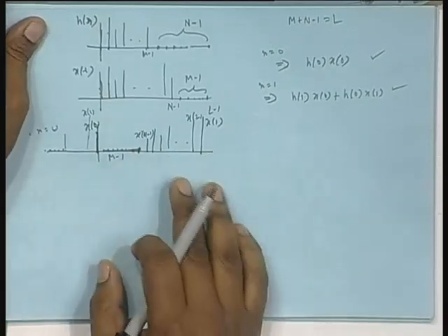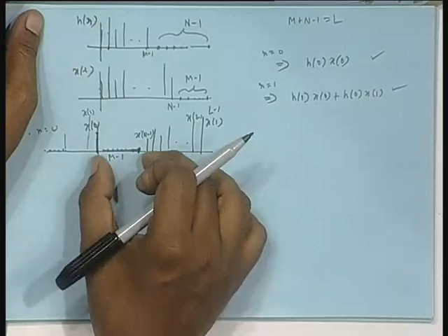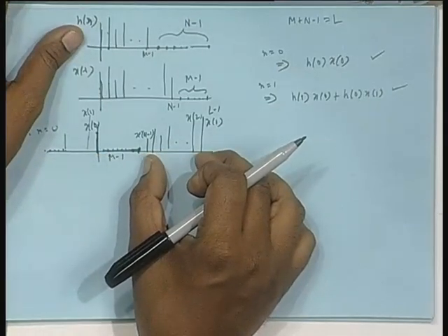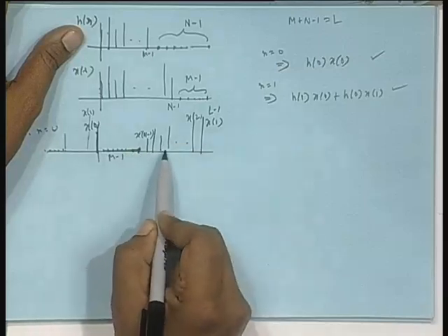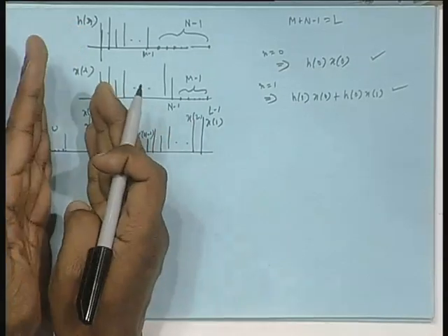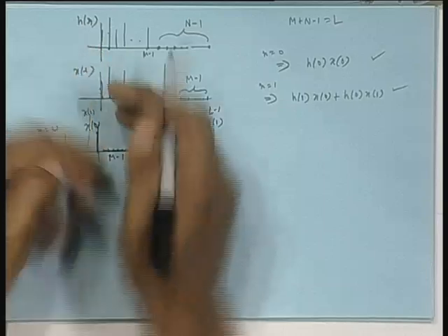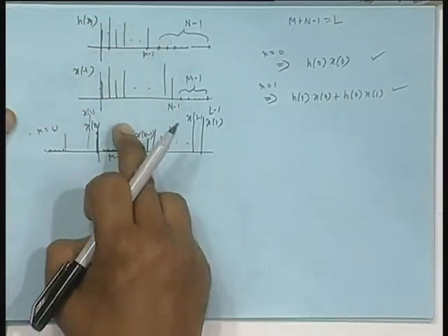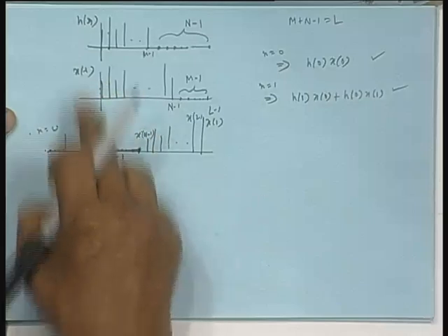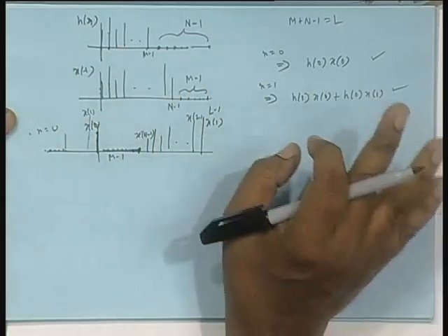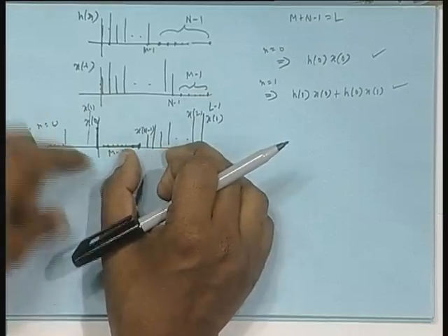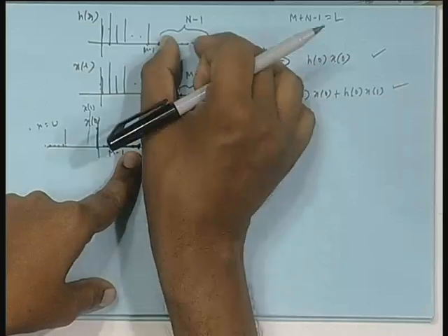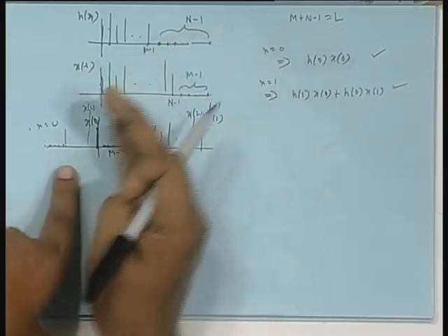As I go on shifting, some data will go out, this 0 keeps moving, 0 comes to this side, and data comes. As long as this data comes here, no problem. They will multiply, like x 0 will move further to the right below h 2, x 1 below h 1, x 2 below h 0, you get the convolution result at 2. Subsequently, part of the samples will be multiplied by zeros, and this sample will multiply by part of these zeros, so on and so forth.